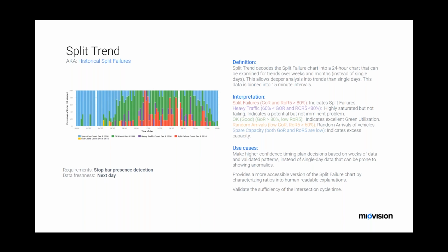It really breaks down how often are phases not terminating properly because they have too much time, or they're just going to the maximum time all the time, and you see a lot of blue, versus how many movements at an intersection, or how many times does an approach just not serve the demand, and then actually alert on those through the intersection health tool. So we rely on this metric quite a bit for our intersection health alerts, as well as our understanding of the progression.